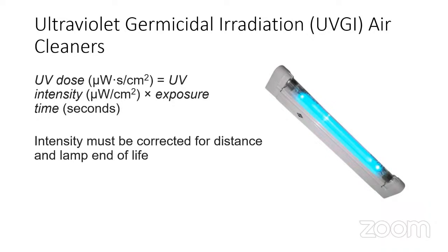So here, how do we calculate the UV dose of a certain UV lamp? Basically, in the data sheet of the UV lamp, they would have specified the intensity. Intensity also varies with the distance. So there would normally be a graph of the UV intensity against distance. Intensity times time is considered as the UV dose, or the quantity which determines how effective the UV lamp is in germicidal radiation.